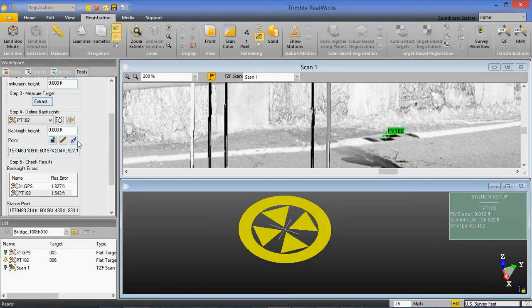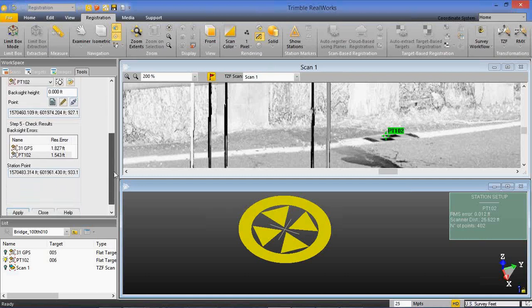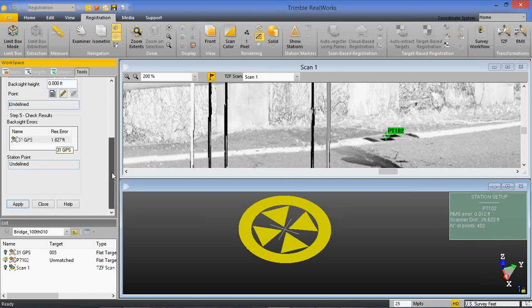If you do create a point here and you want to disassociate it, you think that it's blowing your resection or blowing your setup somehow, you can highlight that, and then you've got these two little, I don't know what this icon is, it looks like 2 rockets or something shooting the opposite direction, but it separates them, so it disassociates the 2 points. So once you've got that assigned, you're ready to complete your station setup and move on.